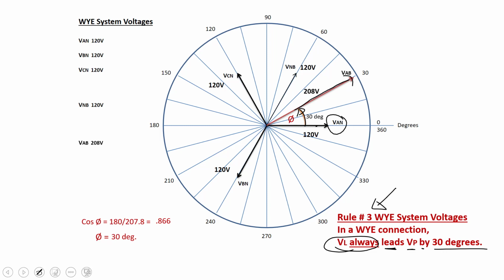But what we're going to do right now, that's due to the position of the windings, 120 electrical degrees between the phase voltages. When we add them up, it always ends up 30 degrees ahead. We're going to try the same thing though. We don't always have to do that cosine sine chart when we're adding vectors. We can use our calculator to do the same thing.